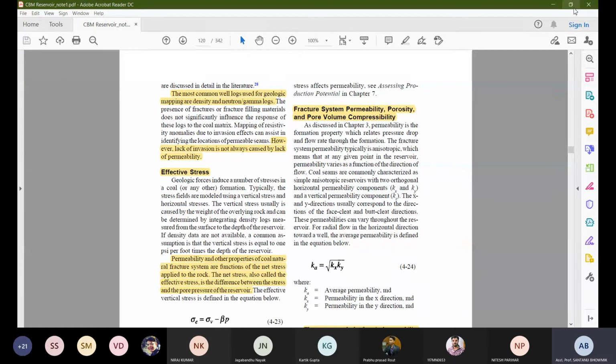we always keep the vertical forces, the load at failure, as the confining pressure increases. You all know that the load at failure will also increase. So, the stress strain graph for a particular rock type is going to be sharper and higher. The rock will fail at higher loads if you increase the confining pressure. Okay, this thing you already know. But